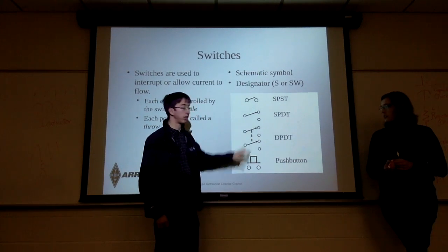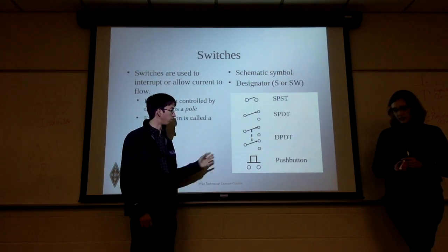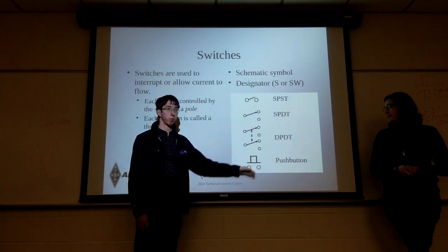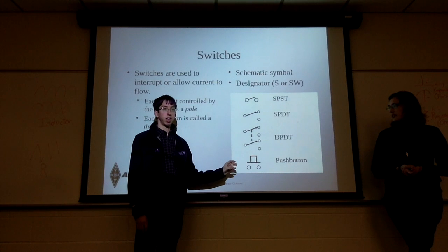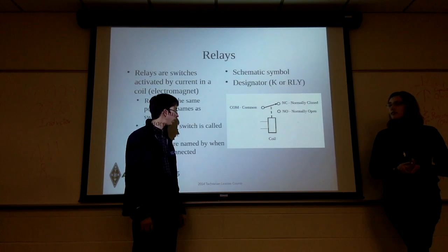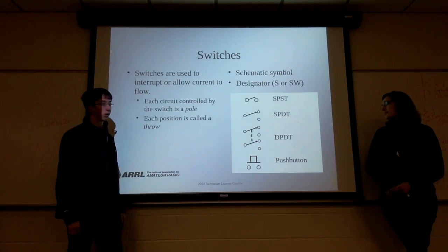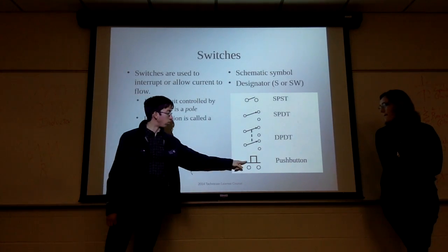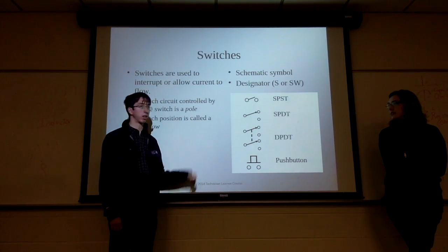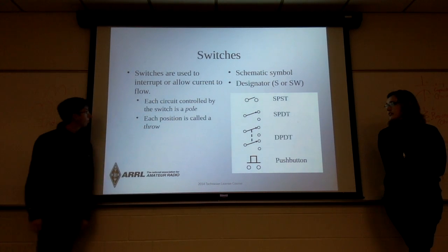That way, when I switch these, the speakers will only be on speaker set 1 or speaker set 2. And push buttons are often momentary. You'll see these advertised as normally open or normally closed, NO or NC. This is normally open, which means contact is only made when you push it, whereas normally closed means the contact is broken when you push it.